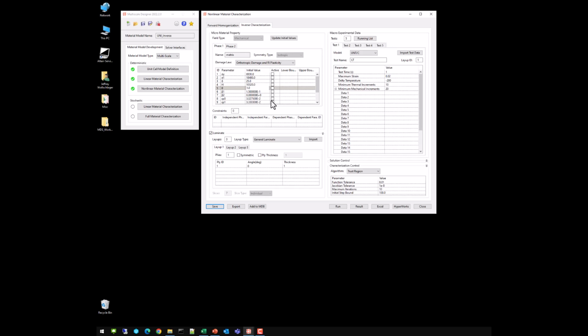Theta of 1, that just means I have no hysteresis. A beta of 0.15. And I'm going to set my plastic strain limits to 1 and 1.1, which basically means I'll never hit them. I don't want to inverse characterize a plastic strain limit at the moment. Okay, and the tangent stress, the delta, and the H are going to be values for which I don't really know.